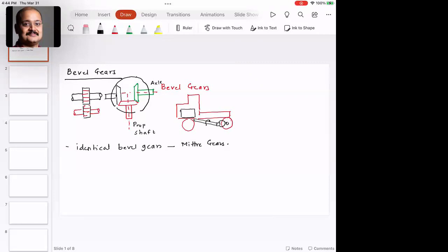As a matter of fact, you won't believe that these 4 steps, coming up with a basic strength based calculation, then coming up with a dynamic load, finding the static load, finding the wear load, and then design some type of a transmission system. These steps are very common when you design the components that are subjected to dynamic loading, or they are power transmission components.